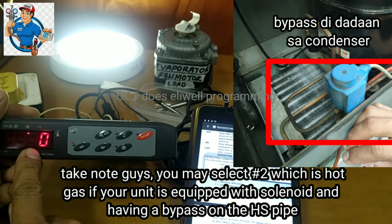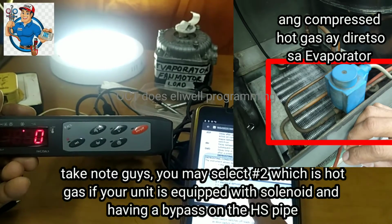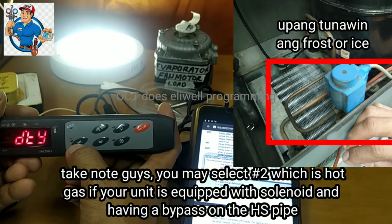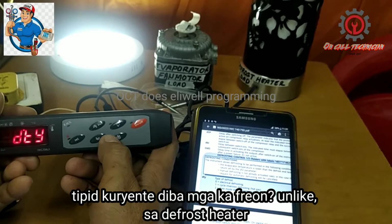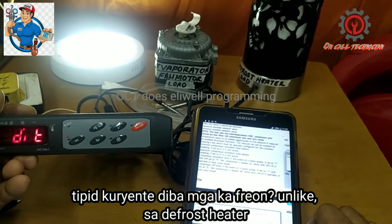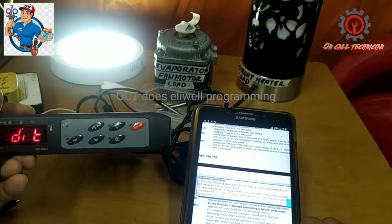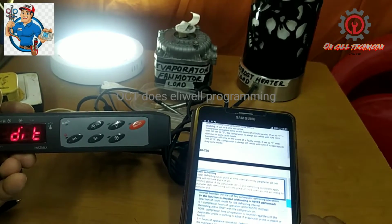This one 0. Okay, so if hot gas, just press 1. Okay, 1. Then let's proceed to DIT. And DIT means interval between start of two subsequent defrosting operation.